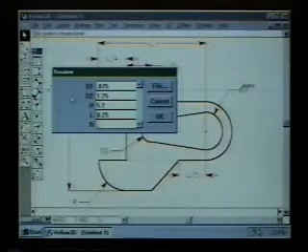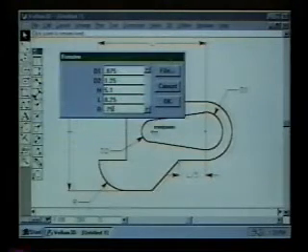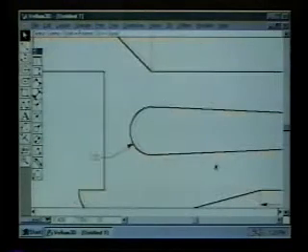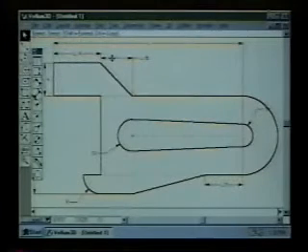R, let's do R of 0.75, anything like that. It doesn't really matter. And then I can select a point to remain fixed if I want. I'll go ahead and fix this point, and then I say OK. And it reshapes and resizes. So I just say zoom all, and there's my part, all resized based on what I typed in. So parametrics is just a terrific tool for doing what-if scenarios and for doing design cases as well.